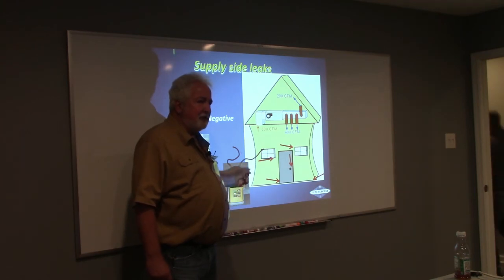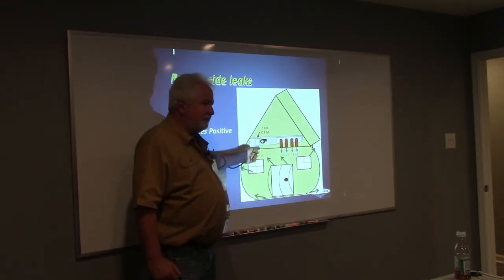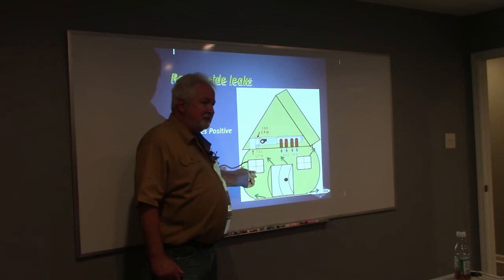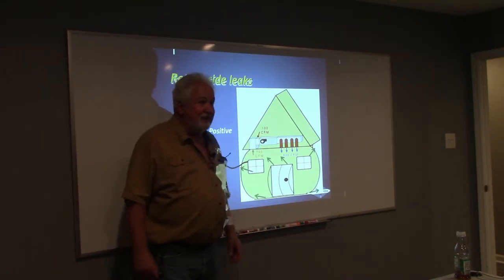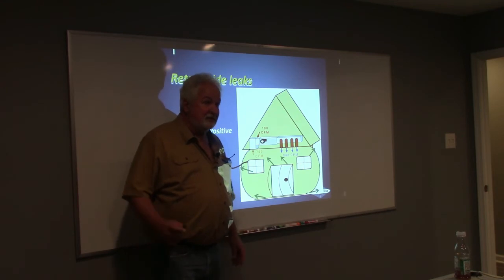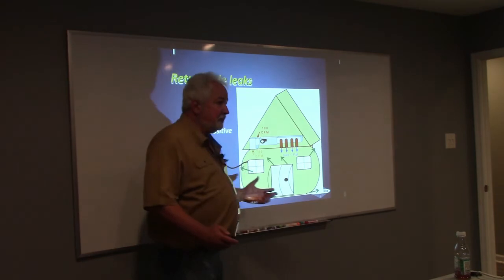How about from every crack and crevice in that house? Because air is coming in, yes? Am I going to suck it in from around the cracks and crevices? No. Am I going to suck it in from the attic? Yes. If dust is coming in the house, it's usually because of duct leakage. Does that make sense? Whether it's supply or return.